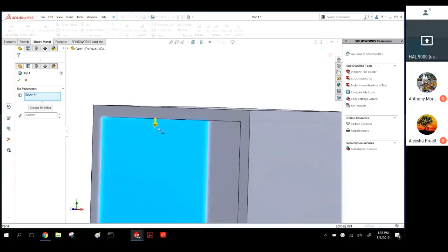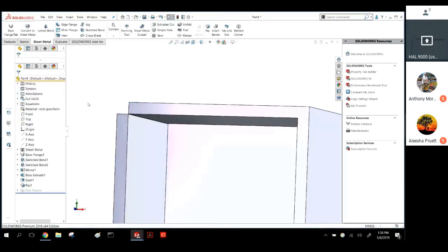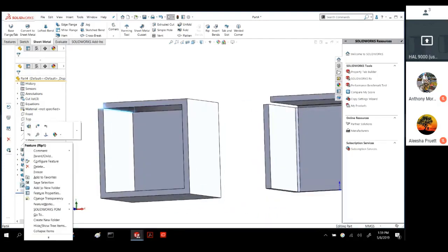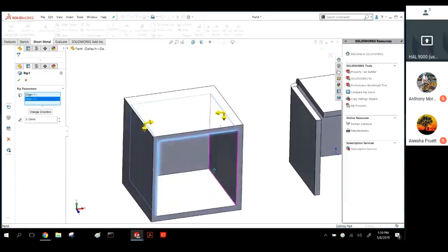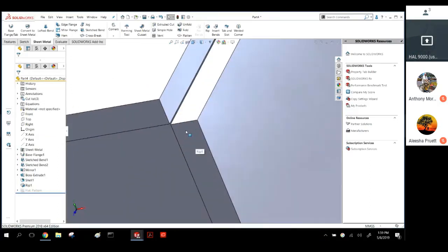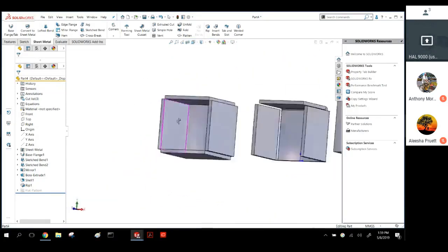So you see that the direction of the arrow is the face that's going to get cut if you're doing that. If I have it where there's 2 arrows, it's not going to do an overlap. It's going to do a butt corner where those 2 edges butt up against each other. And you can do all the corners in one shot. So I can pick this. Okay, I need to tear all 4 of these corners. This is the gap that runs along the inside of that. So that's where that 0.1 millimeter is, how close those are getting to one another.